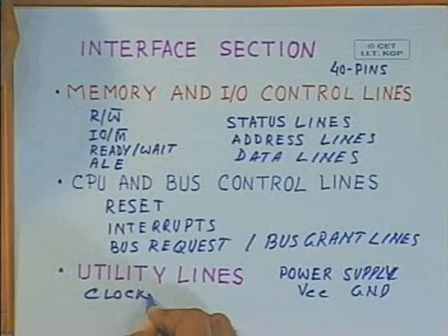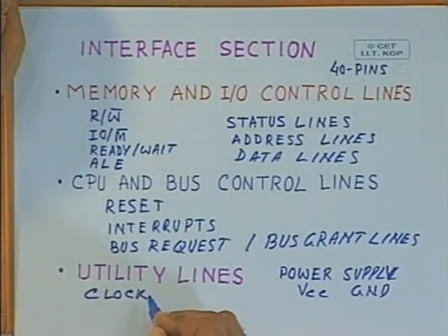So you will require some clock for its operation. So there should be some clock input, or if not clock input, some input for connection of crystal. Oscillator circuit may be inside the chip, but you have to connect the crystal from the outside, which cannot be fabricated on an IC, so that the internal circuitry operates at the crystal frequency.